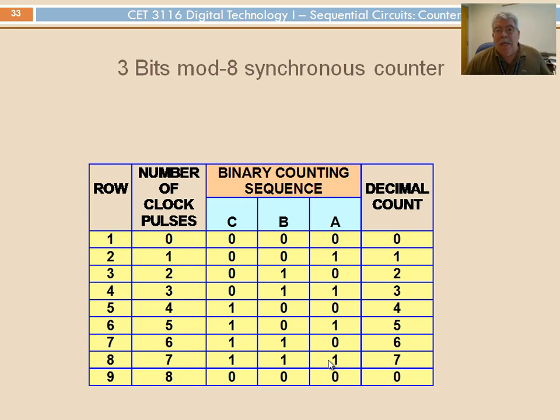Now, see, the approach of the first case of synchronous counters was to make possible that the flip-flop that guides the output is either holding or toggling. If you see this 0, 1, 0, 1, 0, 1, it's clear that this one is toggling in every row. This is toggling in 2.